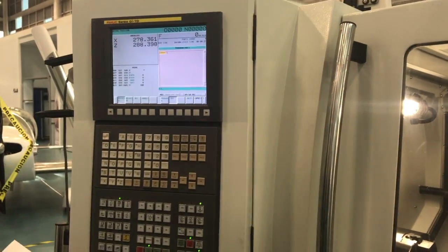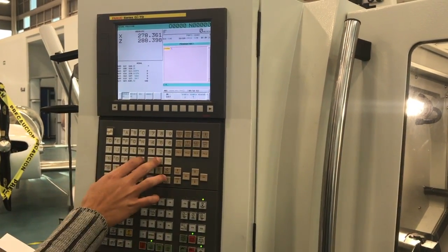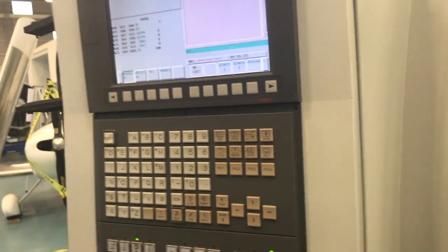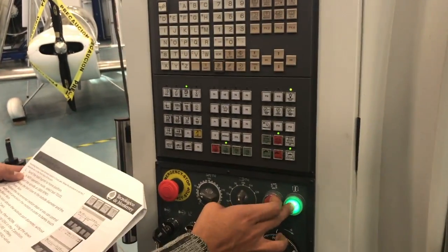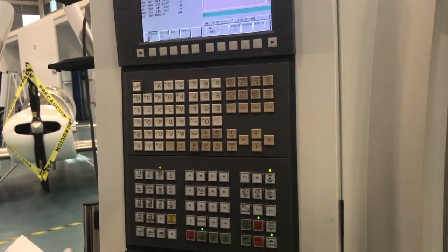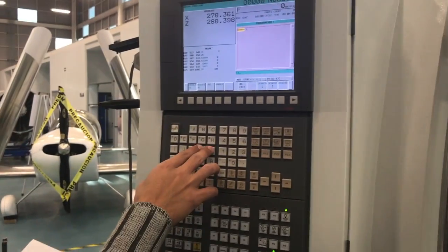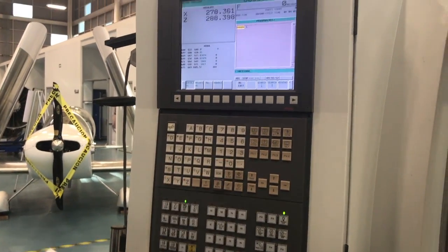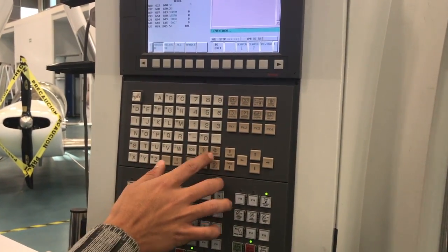Then it's time to set the offsets of the machining according to the manual. Be sure that you follow it right. The first step is we need to select one face tool, in this case T001. Second, we select the starting revolution of the spindle. This information is to get the absolute zero set up properly.